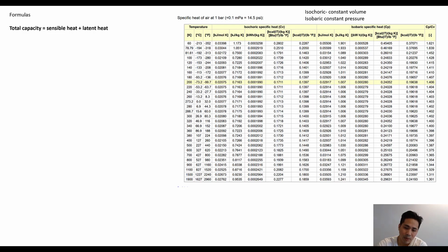And if the wet bulb temperature is higher at a given dry bulb temperature, then the sweat would feel warmer on your skin. So the higher the humidity ratio, the higher the wet bulb temperature, and the lower the humidity ratio, the lower the wet bulb temperature for a given dry bulb temperature.